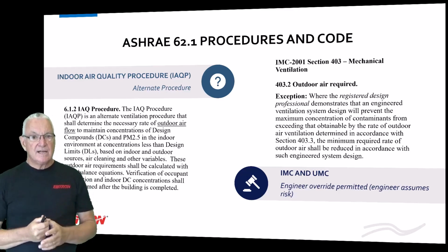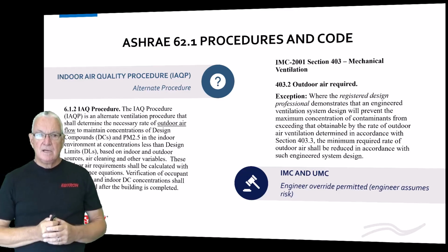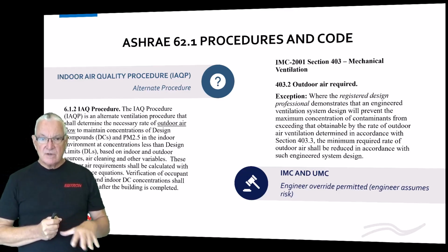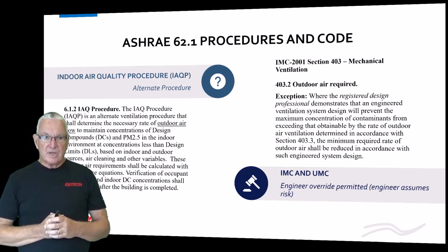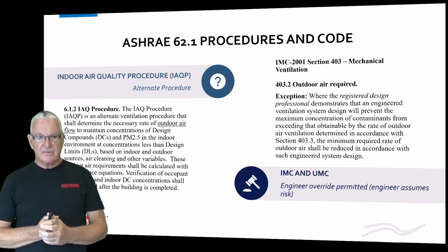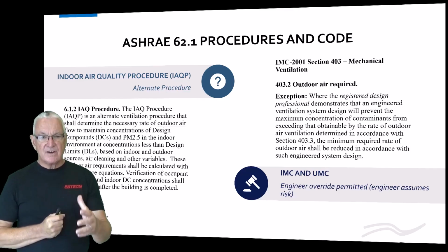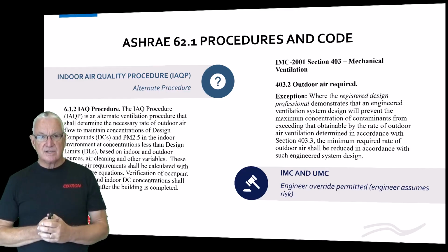Now, the thing that I find interesting that a lot of folks overlook, that happened in recent history in Standard 62, is that last sentence on the left there that says verification of occupant satisfaction and indoor concentrations shall be performed after the building is completed.